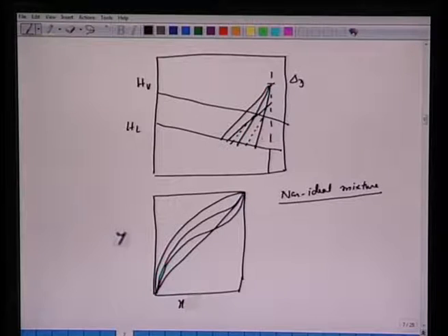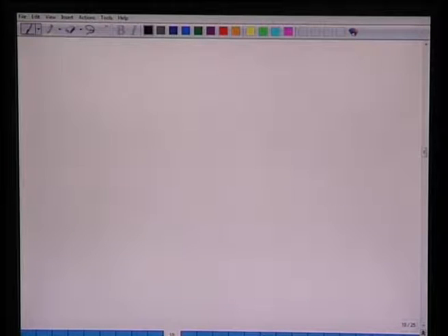In this case, if we have ideal solutions like this, very often it happens that the tie line which goes through the feed, so suppose this is your feed composition, the tie line which goes through the feed composition, and if you extend this, this will give you the maximum R min. All right, so let us try to reconstruct this HXY diagram to obtain R min.